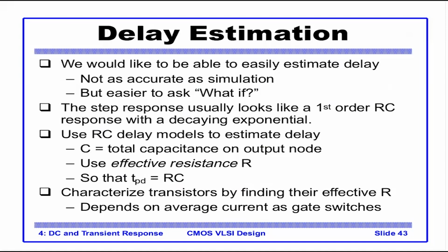So the point here says that we use RC delay models to estimate delay. It's a very useful technique. Propagation delay is proportional to RC. We also characterize transistors by finding their effective R. The effective R depends on the average current that the gate pushes.